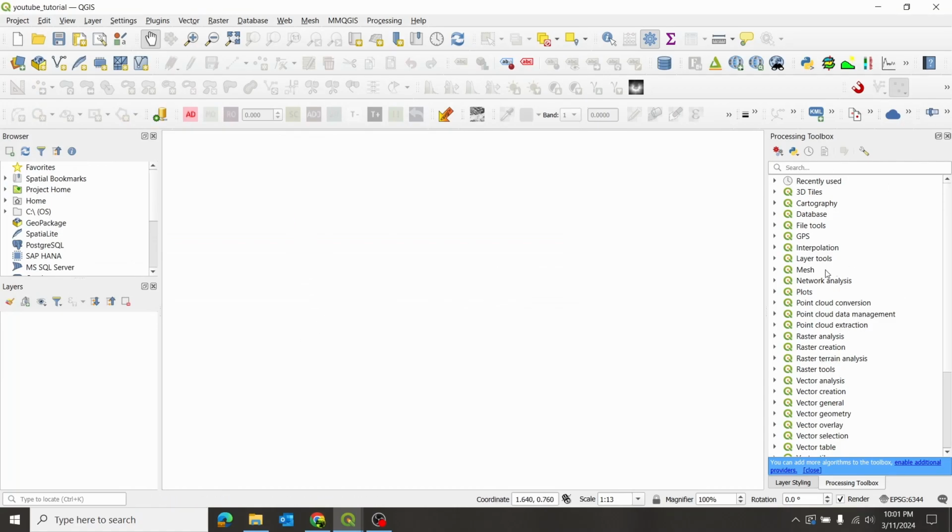So what we want to create from our LiDAR point cloud is a raster. And a raster is basically a picture. I've heard people refer to these as LiDAR pictures online, and that's not a terrible way to describe it. What we're creating is a picture. Specifically, we're going to make a GeoTIFF. Now, a TIFF is just a picture file format. A GeoTIFF is just a picture that is placed somewhere on the Earth in a coordinate reference system.